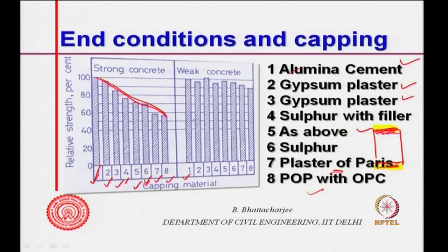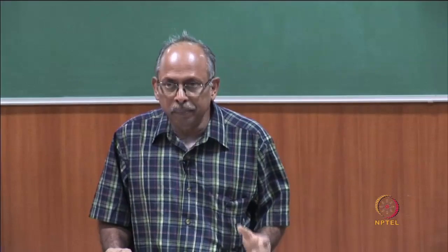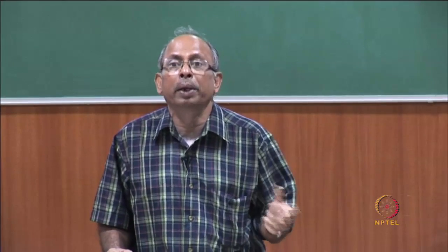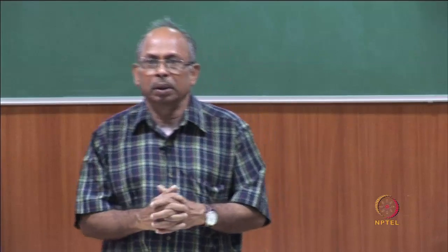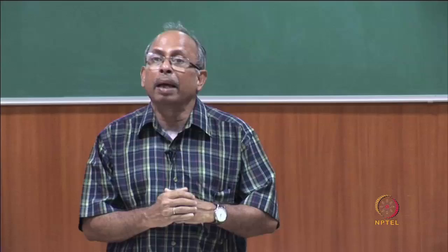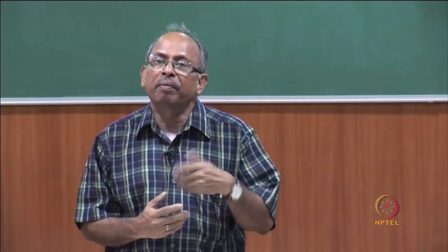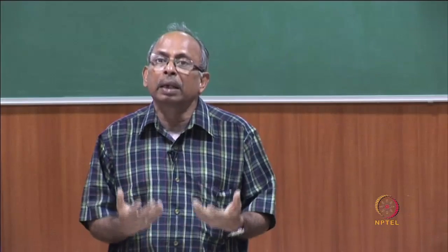and for weak concrete the effect is somewhat less, in fact you find a slight increase. Well, this is a qualitative statement, I am not making a quantitative statement. So, what we observe is that there is a variation and it depends upon the type of capping that you are using. So, end capping has an effect on end condition.